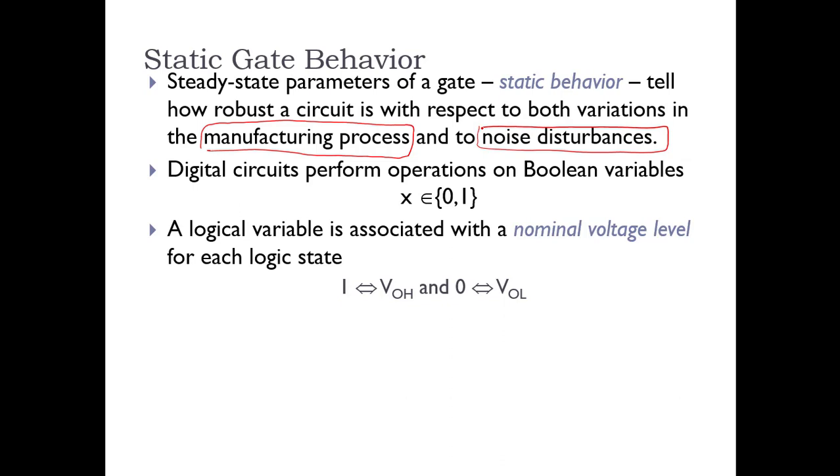What that means, as I told you, is that manufacturing is a very complex process, and they use light to transfer your circuits from the masks to the silicon. Sometimes there can be defects, for example a short circuit or an open circuit, or even minute differences in the silicon.